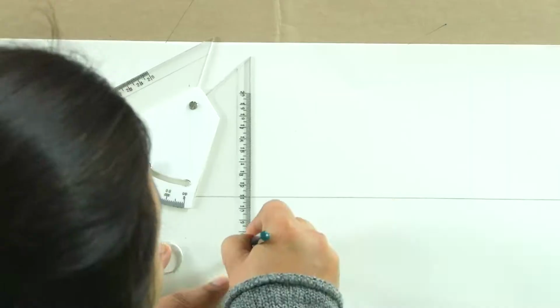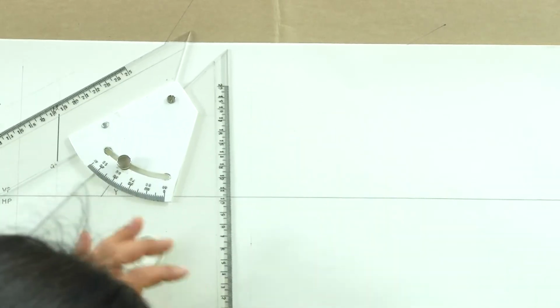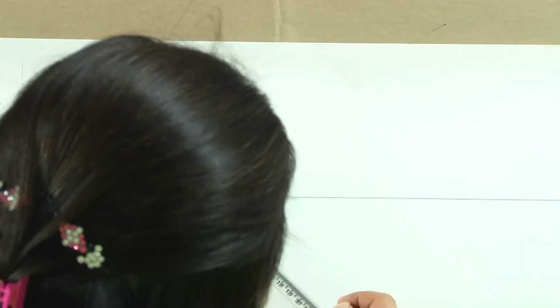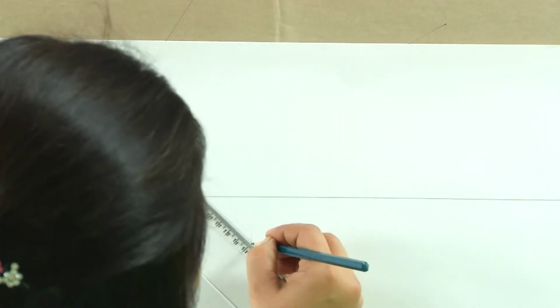We will draw the line starting from a point which is 4 centimeters in front of VP. It is inclined at an angle of 45 degree to VP, which means this. So, there is a line on this incline. We will measure 8 centimeter, which is the true length of the line, and this is what will be seen.